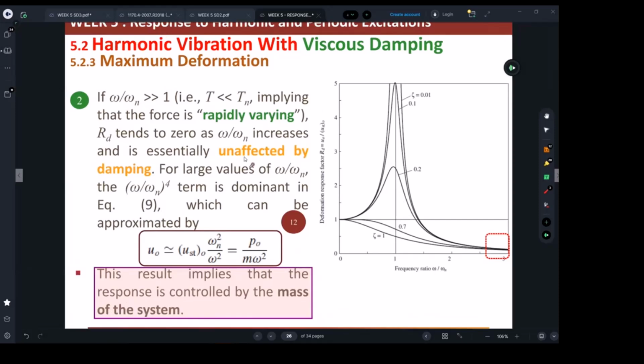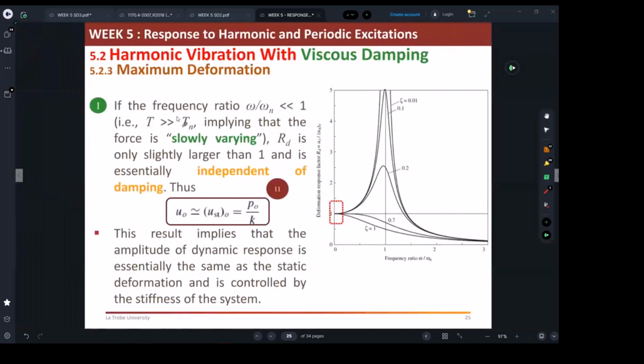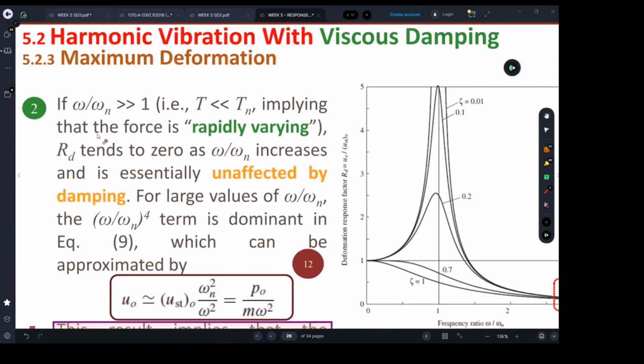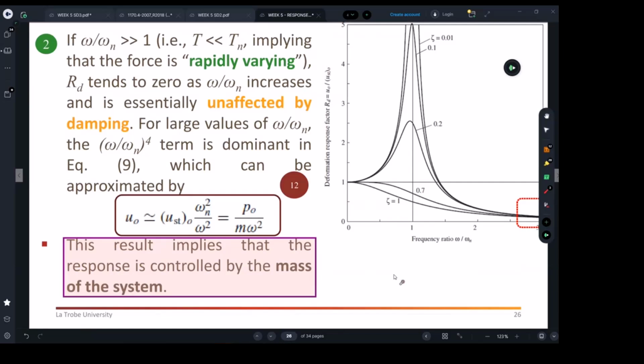Second one. Here is the other way around. Okay, here you've got a very soft building. Oops, sorry for jumping the slide. So the second condition we have here is a soft building being excited by very high varying, or not sure, I don't want to say gentle. The opposite of gentle would be very sudden motions, right, or very shaky ground excitations, or maybe I can say the ground excitation is with very high frequencies.